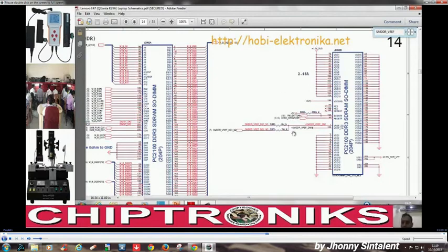And as we know, in a PCH kind of board, the memory controller has moved on to the CPU. So this signal will come from the CPU, and then this RAM will initialize. That is, the RAM initialization process will take place after the CPU powers on, right? After the CPU powers on, when the CPU memory controller gives this signal, that is DDR3_DRAM_RESET, and you can see from where it is coming.